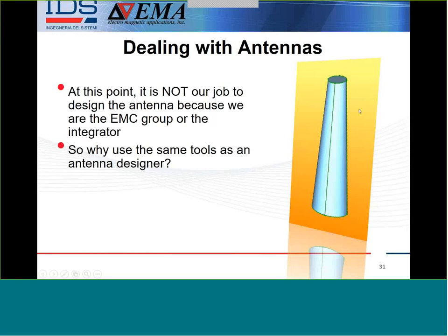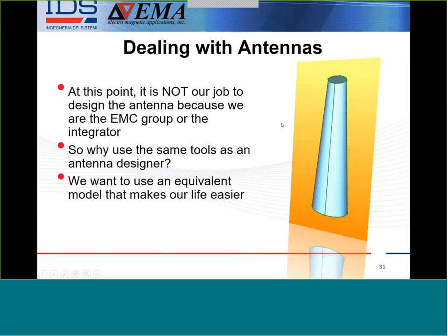Some people do this, but it drives a lot of work, a lot of pain. So what we want to do is use an equivalent model that lets us build something that has an engineering representation of the antenna and what the antenna affects, without having to know all those details of the antenna that we may not know yet, may be proprietary. The supplier may not want to let go of that information.